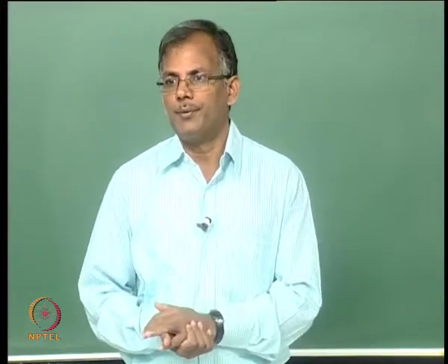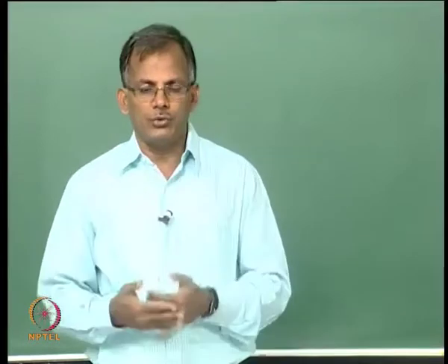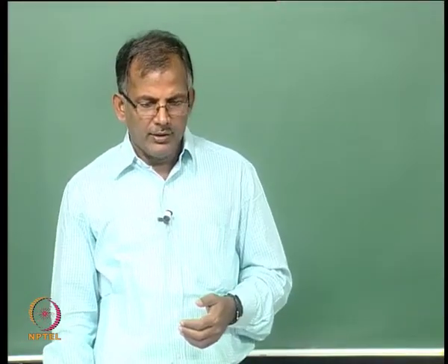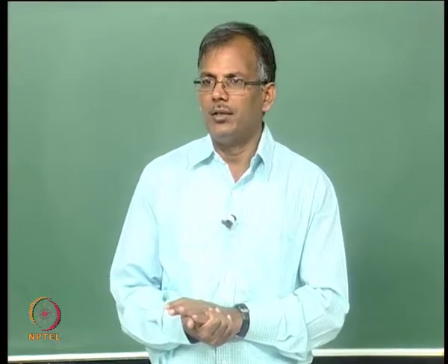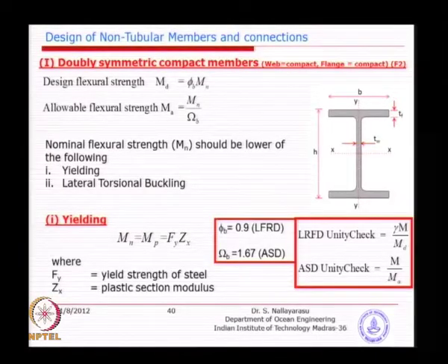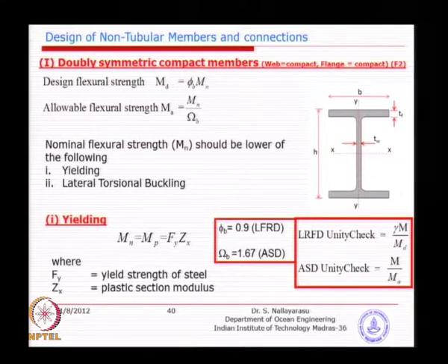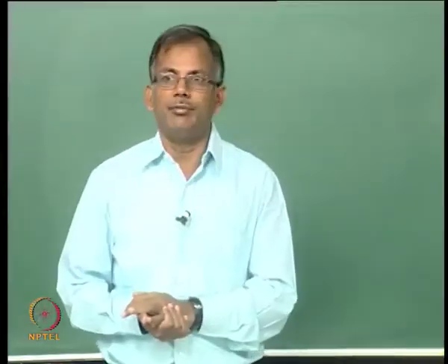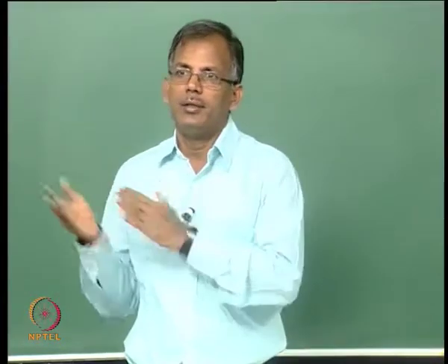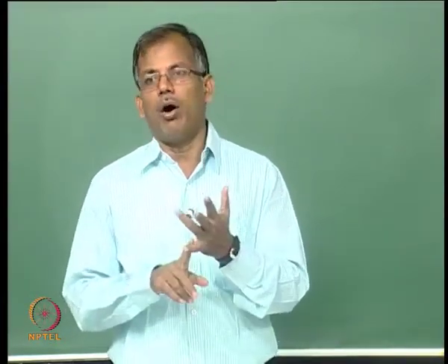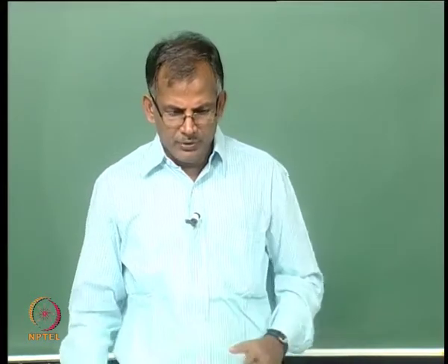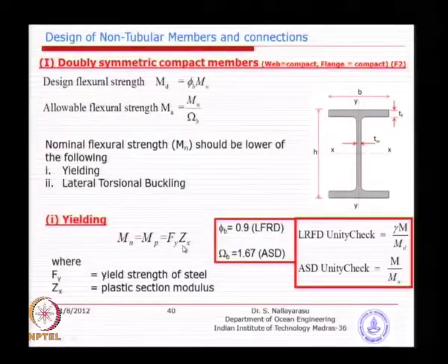the elastic section modulus. But in recent times a lot of studies show that in the form of yielding, it takes higher strength than elastic, and that is where you see this plastic section modulus. As long as the section is governed by yielding, you can go up to the plastic section modulus, which means you are having higher strength. By making the members compact, this is what you are going to achieve. You are going to get higher strength than what you get when you make it slender or non-compact.